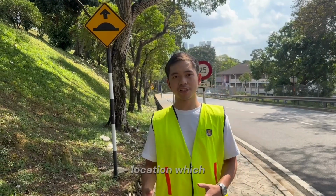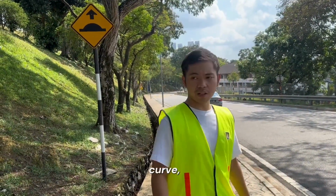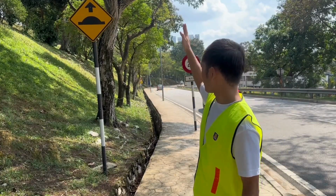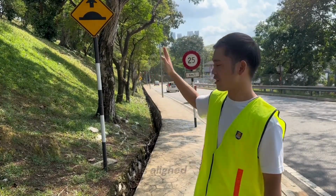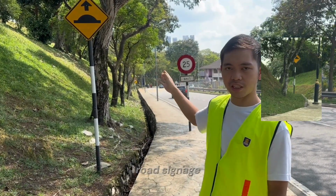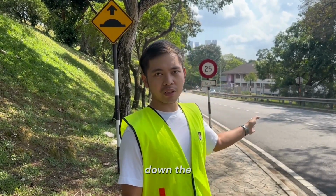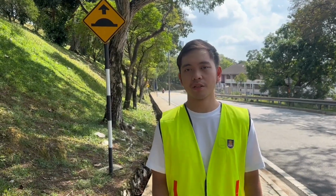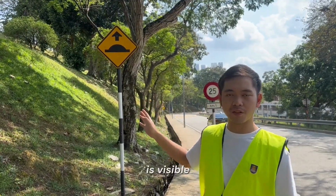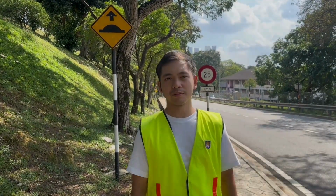At this location, which is near Palapes and English, at the critical curve at the roadside, we found that the landscaping is inadequate and critical. The trees at the roadside are aligned with the road signage, which causes road users to be unable to see the road signage, so they don't know what the hazard is down the slope. As a mitigation measure, we can trim all the trees and make all the road signage visible to all drivers to ensure safety in this particular area.